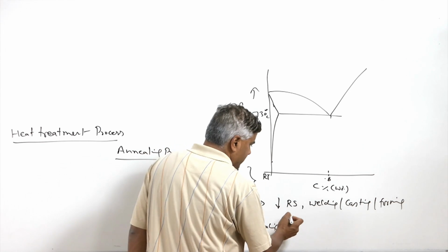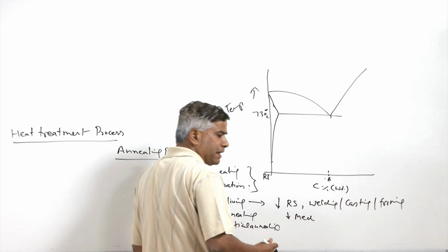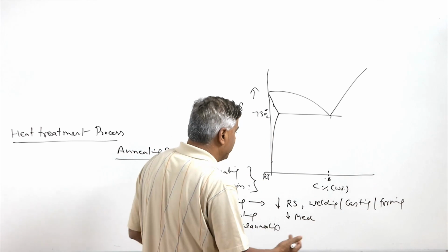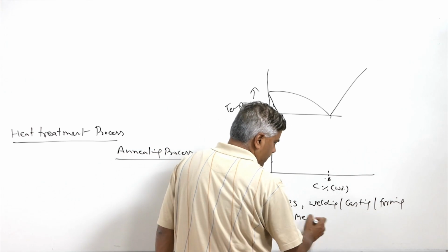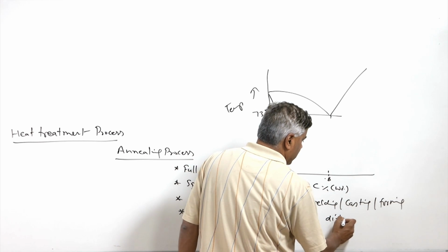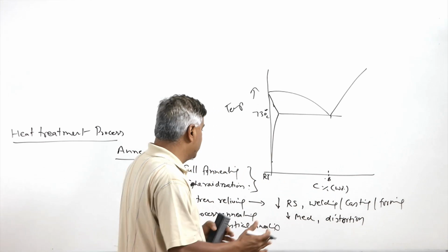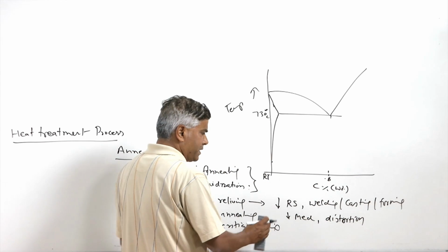These residual stresses in general adversely affect mechanical performance with respect to fatigue life and toughness. Apart from that, they also increase the distortion tendency, and dimensional stability is reduced in the presence of residual stresses.